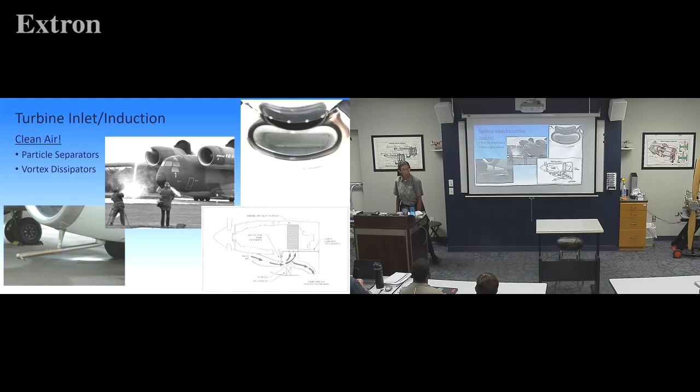And what allows the vortex dissipator system to be activated, or does it just use bleed air all the time? Landing gear actuators. Yep. So it feels weight on wheels, and it's like, oh no, I might be sucking up stone from the ground, and blows it away.